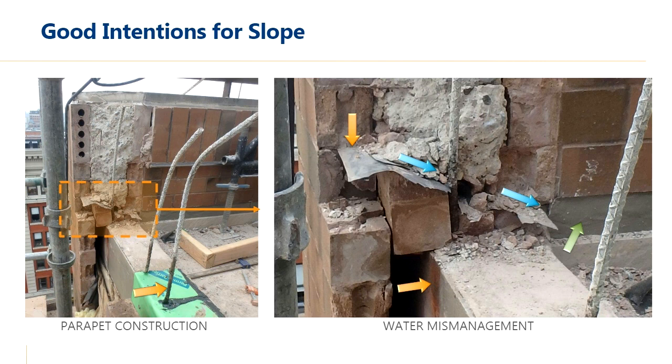If we continue further on that slope, so that rightmost blue arrow, that flashing was sloped to come out onto the balcony, but at some point, someone decided to fill that area in aesthetically, and so here's another place that it got blocked. Also keep in mind, a number of these balconies had those planters, which they had typically gone through and installed waterproofing directly against that wall, blocking this path for water.